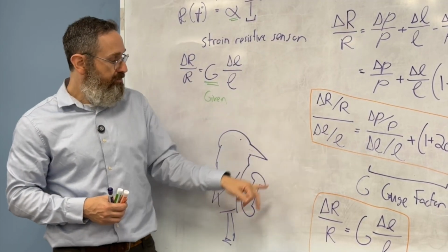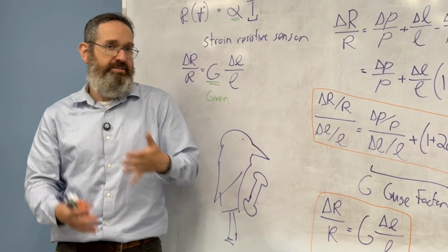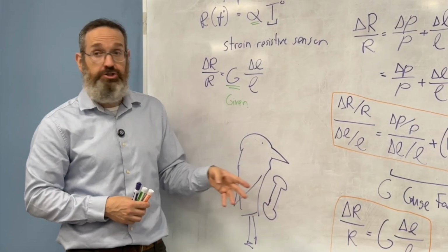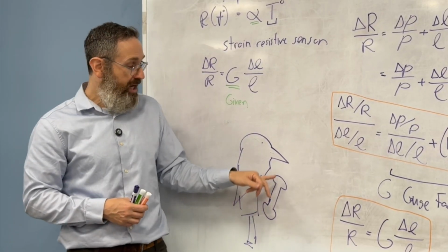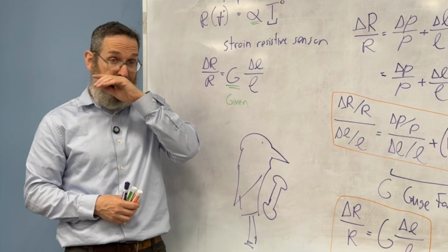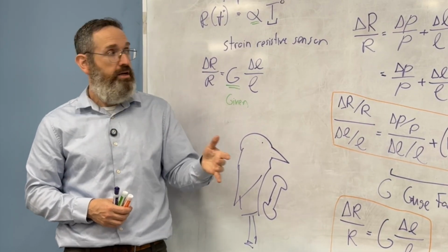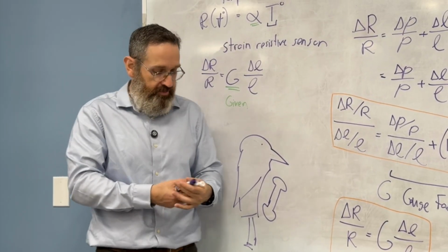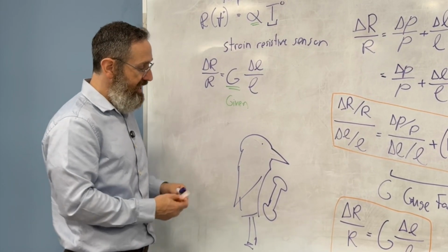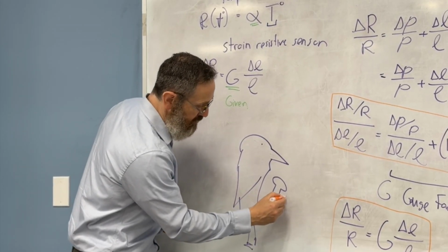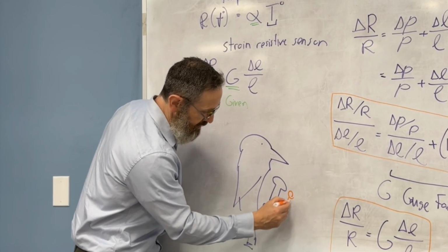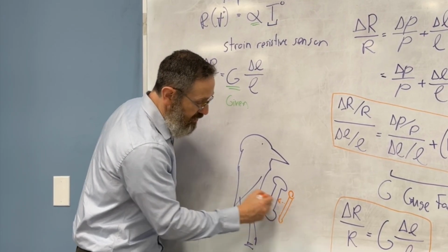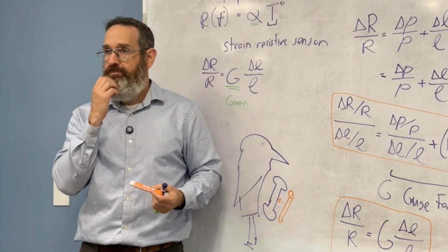And so they would want to measure, for example, as this chicken walks, as it's exposed to some sort of stress, right, an accident, what is the strain on this bone? Now, the way you would do that, and this is not a hypothetical example, there are labs that do that, is you would need to use a strain gauge, right? That's the sensor you want to measure. But I want you to notice that when you use a strain gauge, I'll draw this as a tube here, you're going to have to attach it to the bone, right?